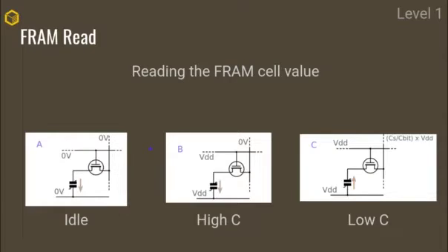Now, to read, I'm actually going to set my bit line to floating, which means that if I don't explicitly drive it, which means apply a current, either by connecting it to the ground or connecting it to my power supply VDD, if I leave it floating, then based on the value of the lines it's connected to, I would change the voltage on it.